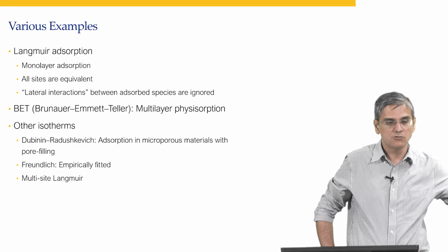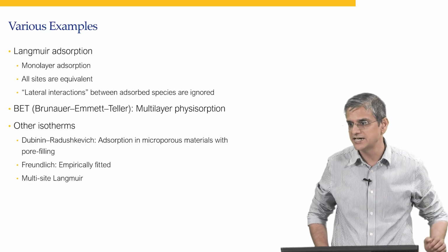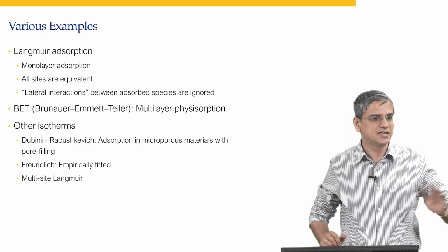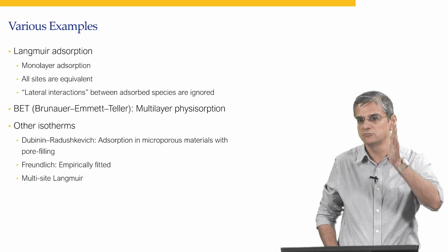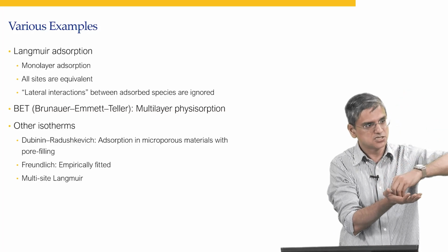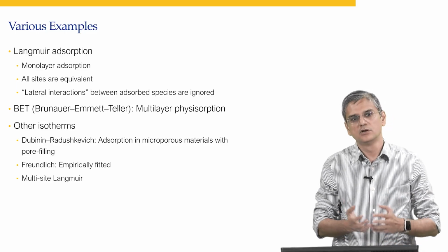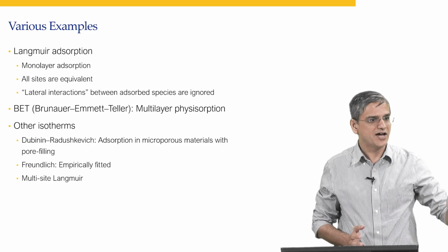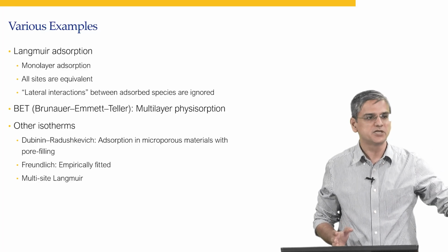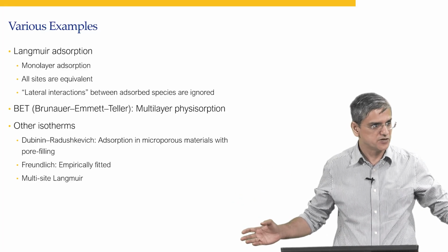What we have talked about is Langmuir adsorption. There's something called multi-site Langmuir. There's another adsorption called Unilan, which is basically Langmuir adsorption. Langmuir adsorption will be that A adsorbing on a surface will have one particular value of delta H. In Unilan, the value of delta H, heat of adsorption, will lie between say 3 kcal to 4 kcal as a probability distribution function.